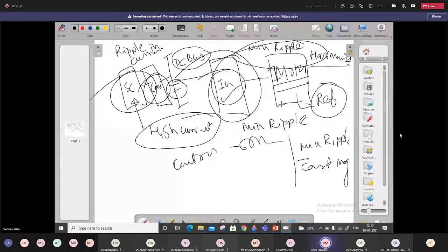One more, sir. Can an ultracapacitor work as a constant voltage source for some time? It cannot. Of course, for a small period of time I can assume that, because the variation in voltage is not that fast, as it is related to your SOC. It cannot vary at a very fast rate with respect to time.